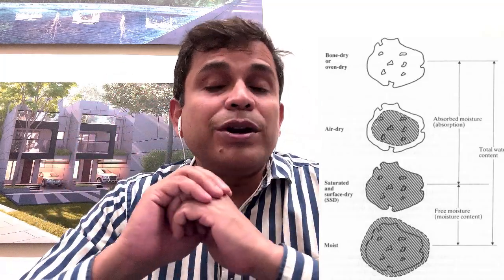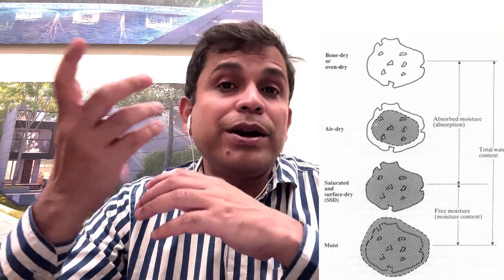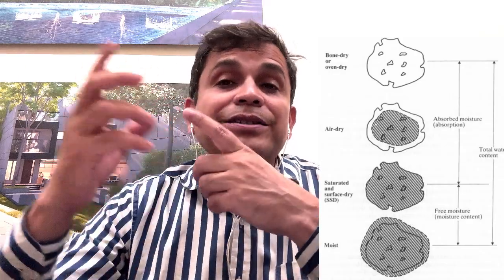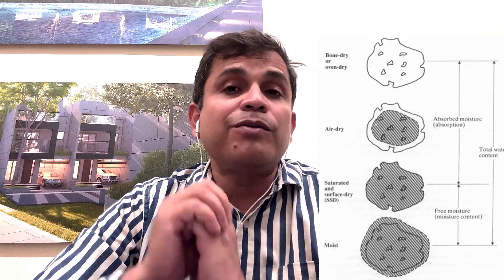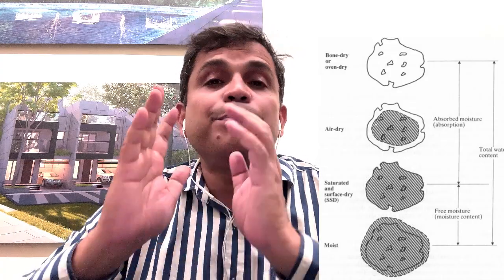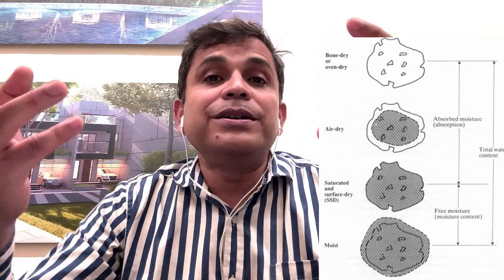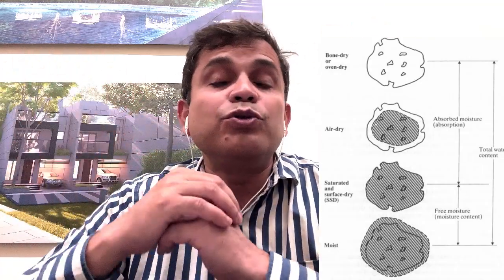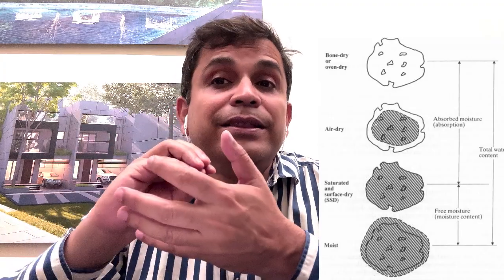In this condition, what is happening? If we are adding water to the mix, the aggregate is neither taking water from the mix nor contributing to it. So this is the ideal condition, but practically it is impossible. We cannot get the coarse aggregate or the fine aggregate in this condition or the surface saturated dry condition.